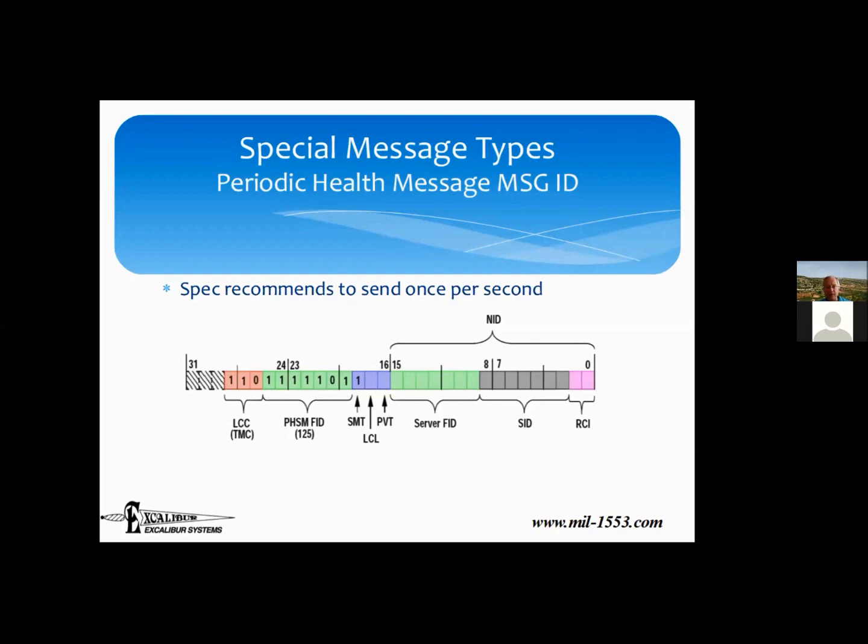On a health message, I don't care about that so much, but I care about physically, who are you? So that if I have, for example, 4 inertial navigation systems on the aircraft for redundancy purposes, on a standard data message, they're all the same. I don't have to distinguish them because they're all giving me the same kind of data, and that's what I care about. Am I getting the altitude or not? Whereas if I want to know if a box is healthy or not, what I care about is physically, are you the first, the second, the third, or the fourth? Because if one of you is going to be sick, I'm going to take you off the bus.